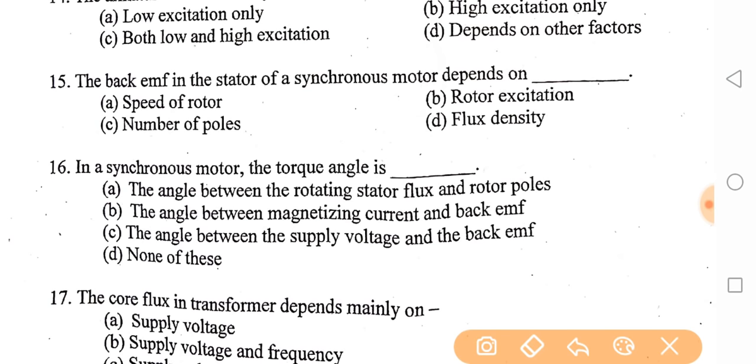Next question is, in a synchronous motor, what is the torque angle and in between what? The torque angle is made by what? So the right answer is A, the angle between the rotating stator flux and the rotor pole is called the torque angle in a synchronous motor.